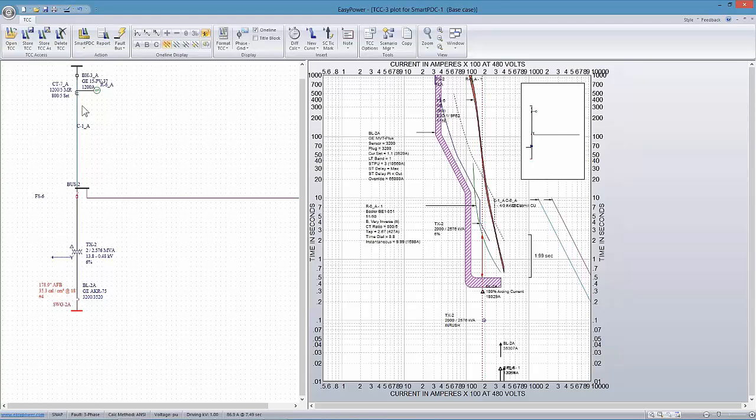So then the next question is, where is the fuse in all this? The fuse switch, which is right here. And the tool, obviously, SmartPDC can't make adjustments to the fuse, but it can show us the effect of using a different fuse. So what this is showing is the fuse operation is too slow to be a deterrent or a protective device for arc flash, and it's obviously in the circuit for protecting higher current for longer periods of time.